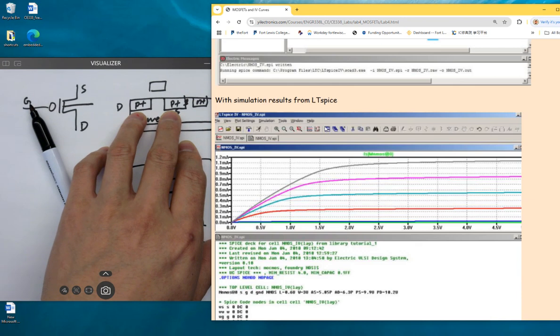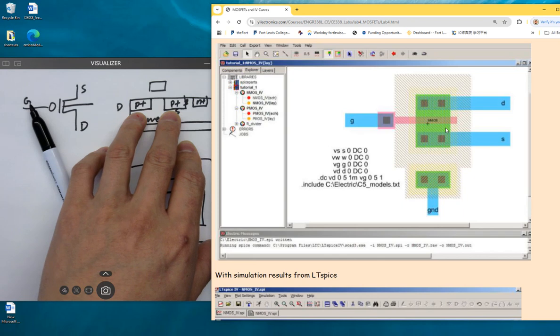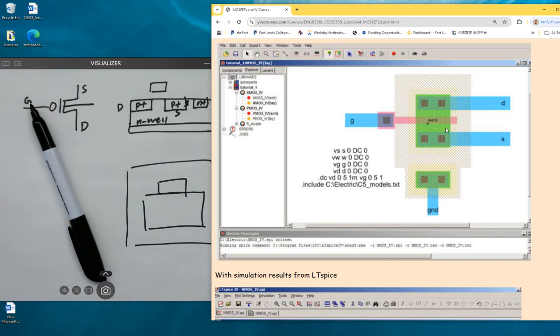You can tell that from the layout here. Did you see any difference? Keep in mind, this is the mask. So this is a physical design eventually being put onto the wafer. And you don't see any differences between source and drain. Same material, same masks. Make sense? So they are the same nodes, but you just use one of them. You label them as the drain and source. It doesn't matter, depending on how you connect the voltages. So we'll see how these transistors are operated later.